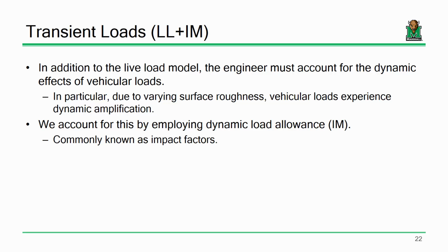All right? When we do live load analysis, we have to be realistic about things. And one of the parameters that we have to assess is the idea of dynamic effects. What I mean by that is when we do a structural analysis problem, there's a beam with 20 kips sitting at the middle, and we just assume it's been there forever and that load is static. That's not how bridges experience loads.